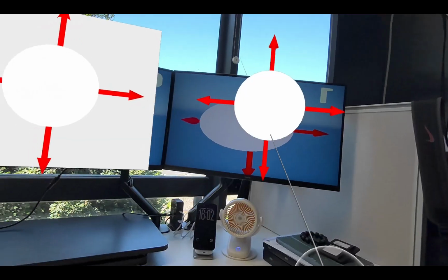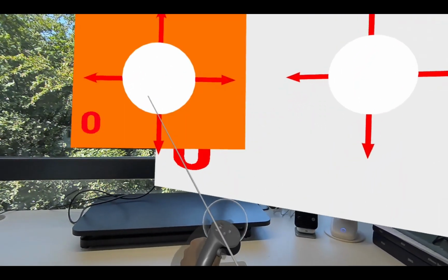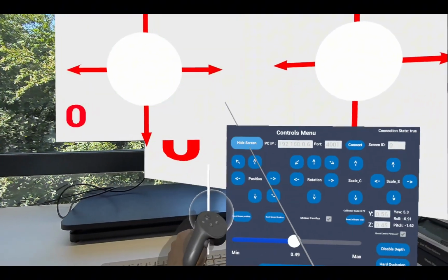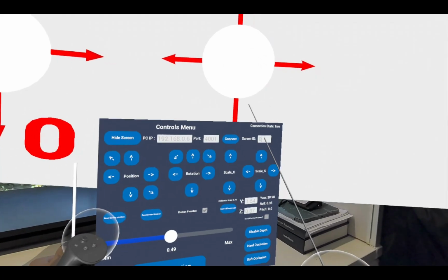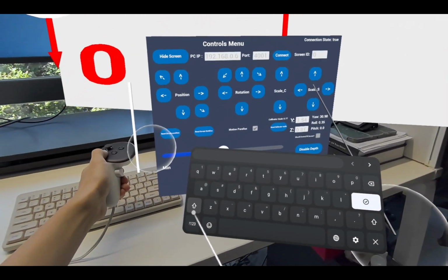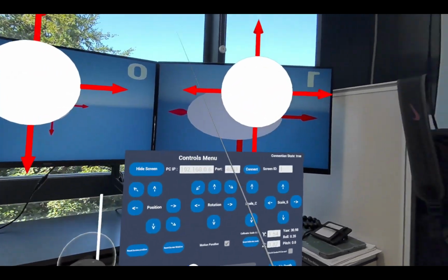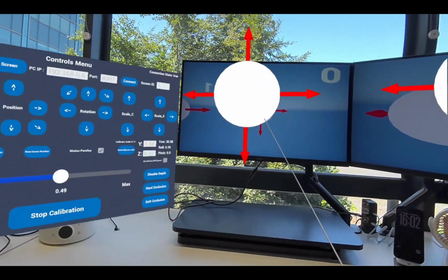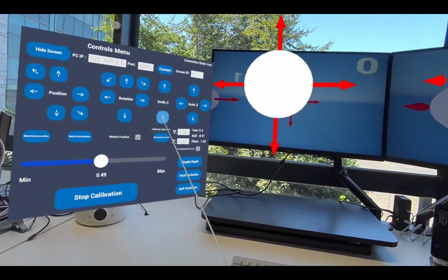The calibrator on the primary screen is used to calculate the relative transform applied during subsequent synchronization. Therefore, accurately calibrating the primary screen is particularly important. Change the screen IDs on the HMD so that they match the corresponding screen IDs in the PC nDisplay configuration. Next, adjust the size of the calibrator approximately and align the primary screen with its physical counterpart.